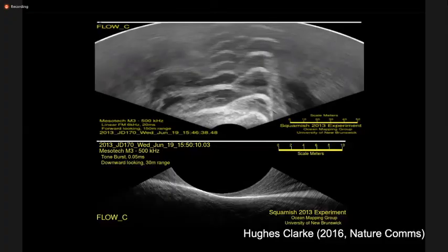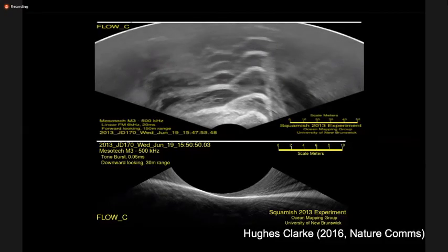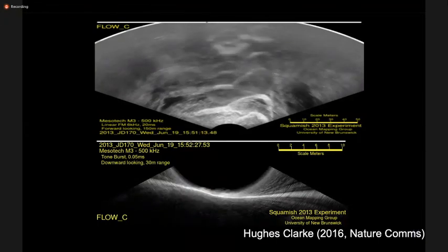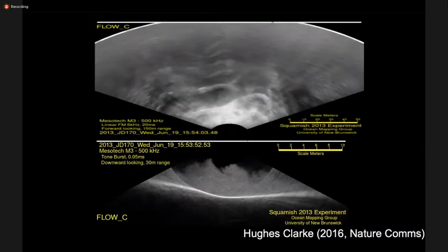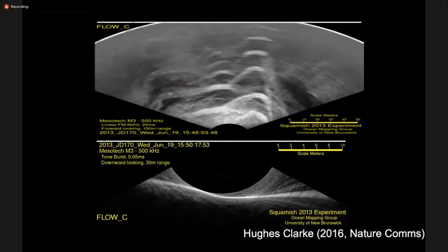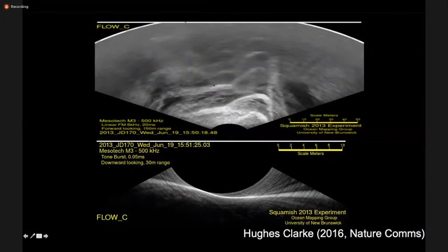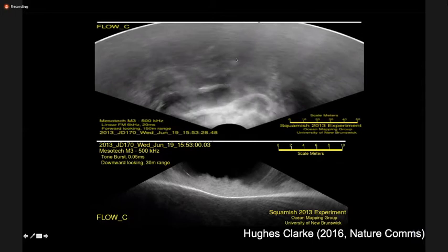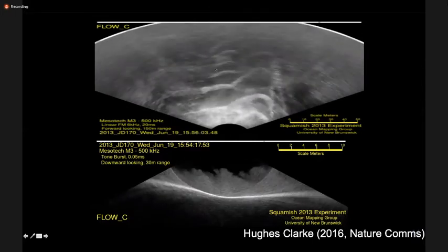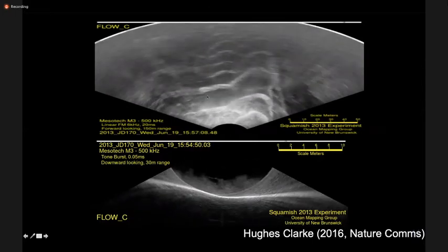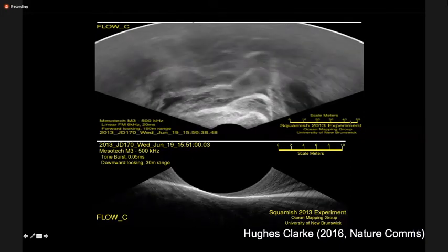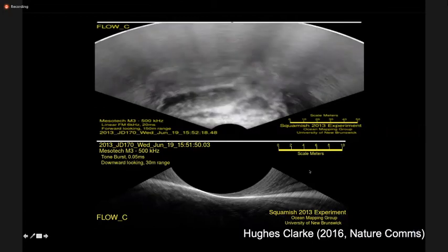So here, the top image, we're looking at backscatter. This is energy that's returned from the sonar. The white is high backscatter, the black is low backscatter. And so where we have suspended sediments in the water column, they shine as white. So what you're going to see here is a relatively dilute flow coming through, and then further on another flow, moving about 2.5 meters per second, that cannibalizes that flow, and it interacts with these bed forms, these crescentic shaped features within a submarine channel. And for scale here, we're looking at about 50 meters across this yellow bar.